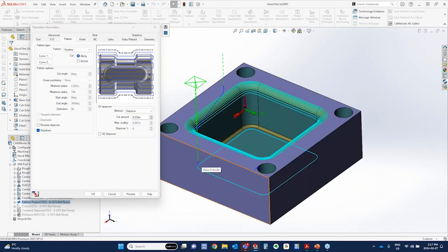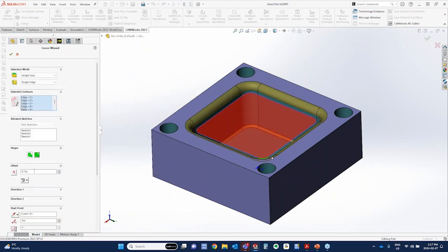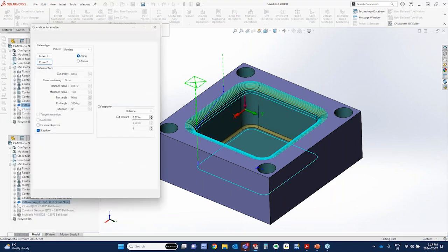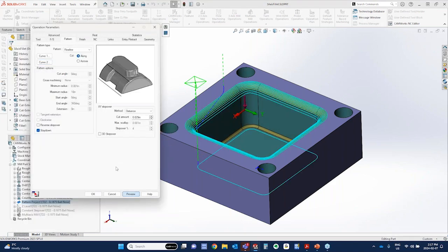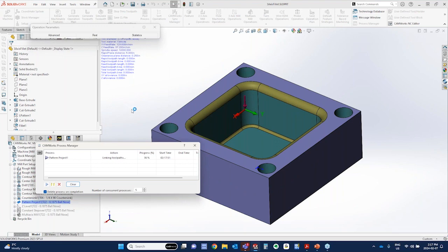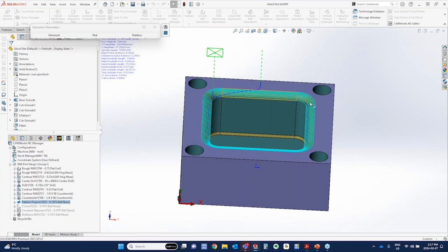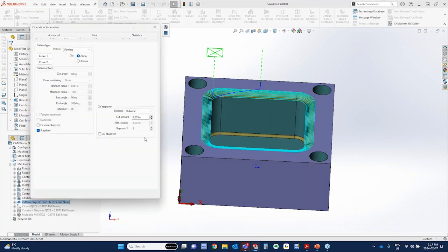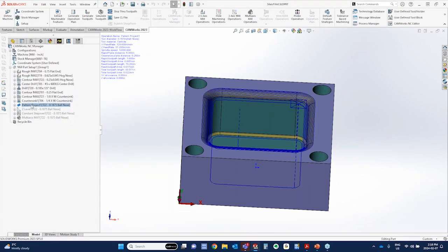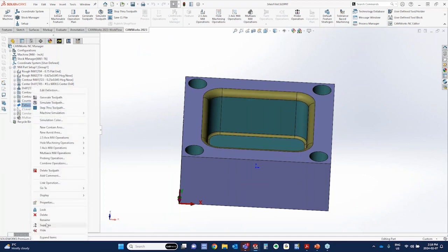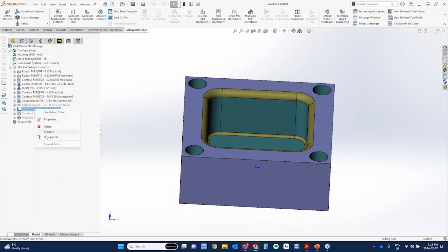You can actually see it's come down onto the floor here, so I could actually adjust where that's cutting with curve 2. So this one's actually offset 0.1, so I could say 0.05 or something like that, to limit it to where that toolpath is being created. So that's the pattern project toolpath. It is now just staying on that fillet. So that's one option. Another option, so I'll just suppress that one and bring up the Z level.